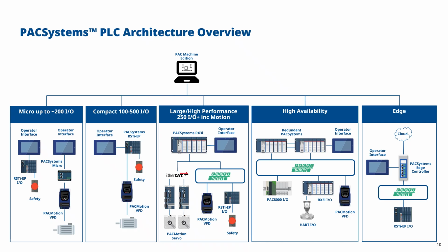And the last one on the right, we have edge capability. So this would be a simplex or redundant edge controller application using our CPE 400 and CPL 410. Again, optional operator interface. Because it's an edge controller, there's quite likely integration up into the cloud. And then we have a variety of different sorts of I/O, typically for RSTi-EP, but again, other types of I/O are also supported, depending on what sort of control you have and how much I/O there is. So we don't have a recommended I/O count for edge controls.